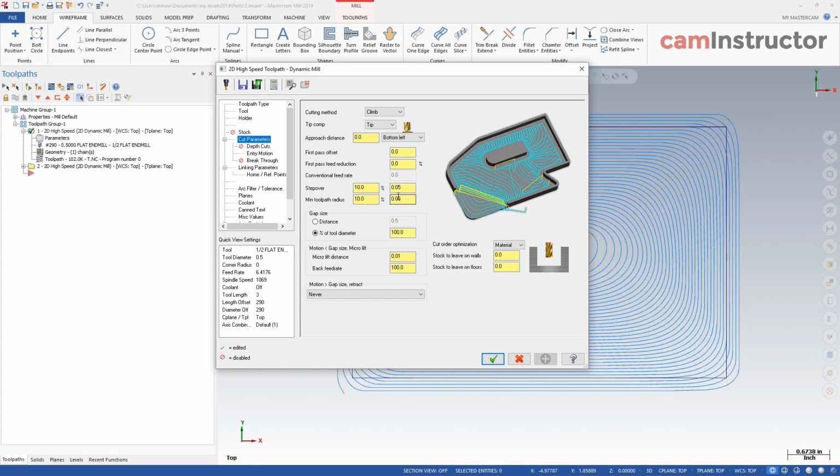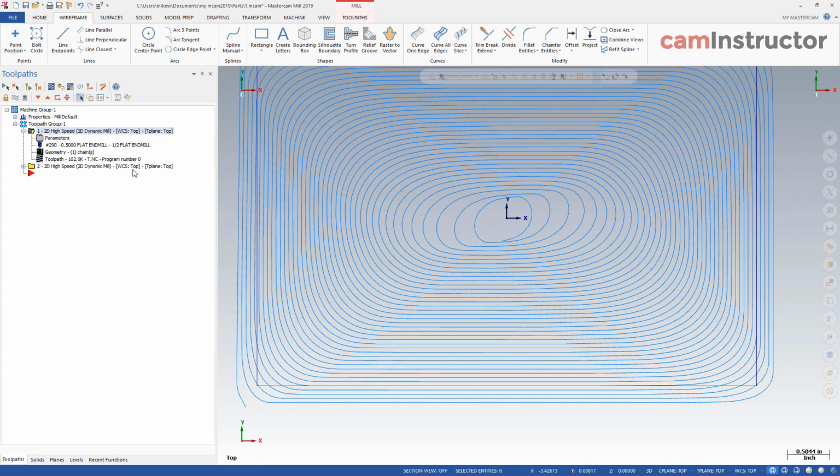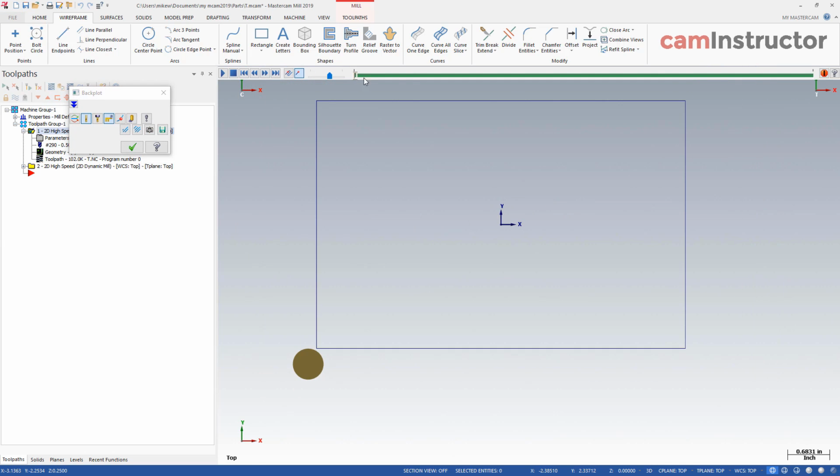You need your cutter, no matter the shape that it's cutting, if it's in this corner here, if it's cutting way across a wide open area, that tool engagement needs to be consistent. So that tool engagement will equal tool pressure, deflection, tool load. All of that will remain constant given a constant amount of cutter engagement. So even though you're seeing this in your toolpath, don't think that the toolpath is doing something buggy. This is intentional.